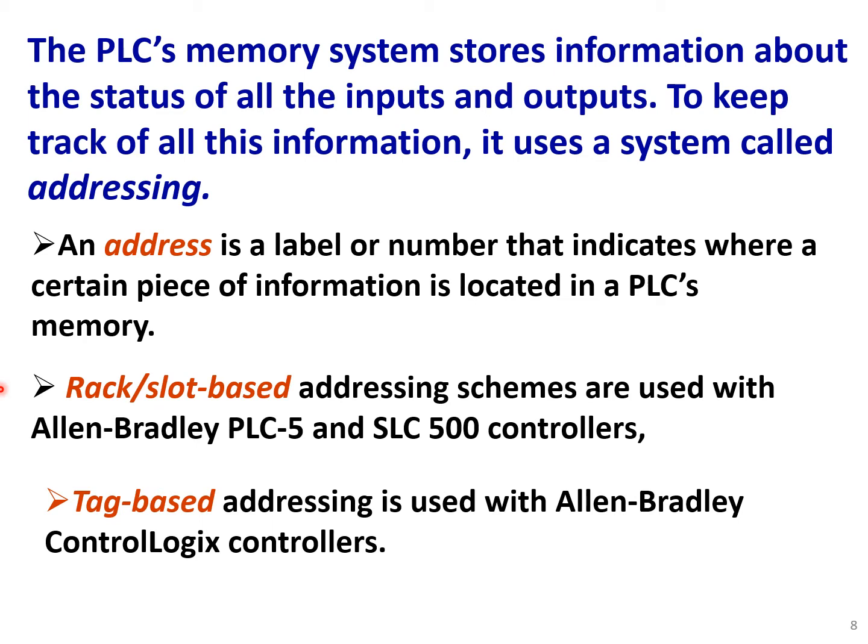Rack slot based addressing schemes are used with Allen-Bradley PLC5 and SLC500 controllers, and tag-based addressing is used with the Allen-Bradley ControlLogix controllers. So these are two different types of addressing methods.